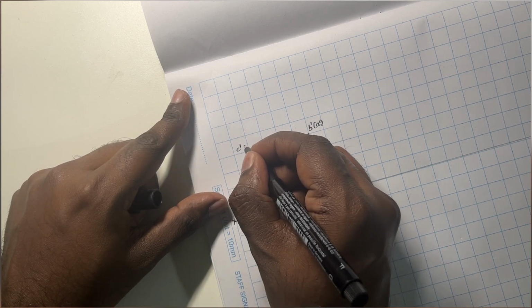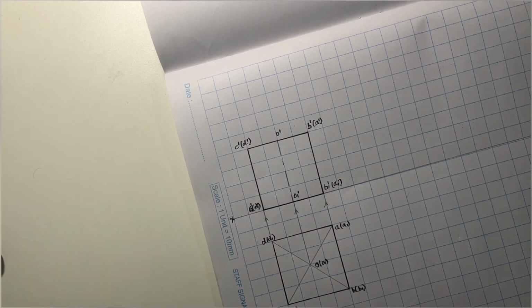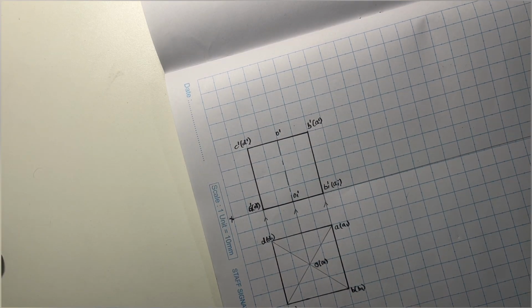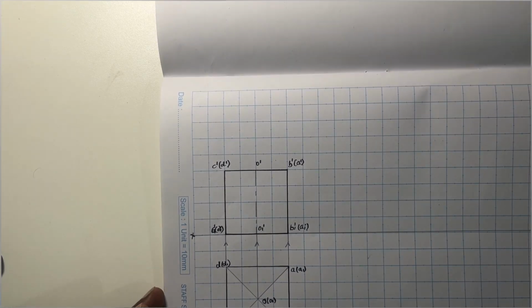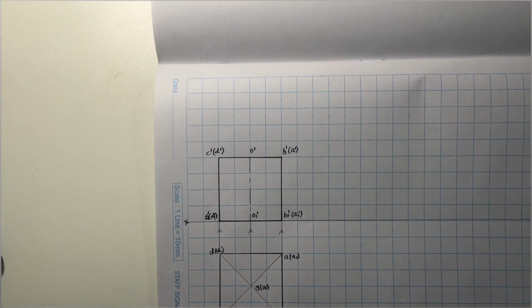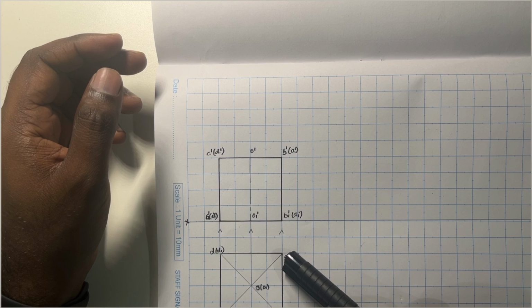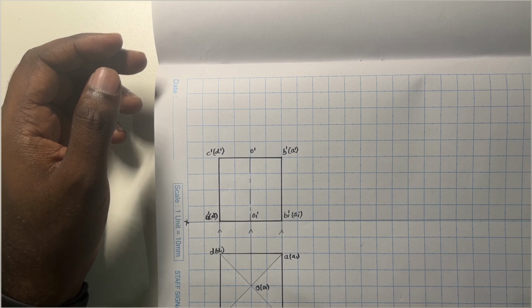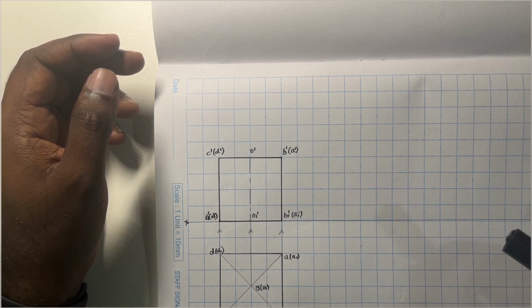And similarly here it is C dash and D dash, because the corner C is visible first when the observer is going to look from this particular direction. So the front view and the top view of the first position is complete for the cube. As per the problem statement, it is a cube of 40 mm which is resting on HP on an edge, and this edge is going to be inclined to the vertical plane in the later stage at an angle of 30 degrees. Okay, so now we'll move on to constructing the second position.